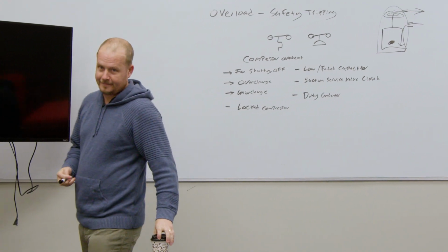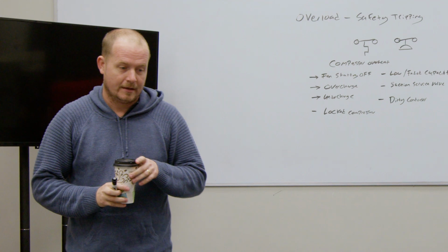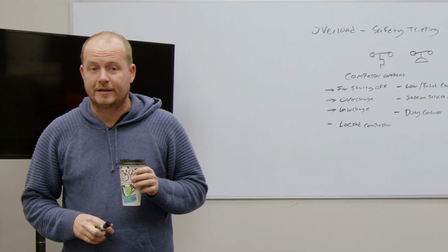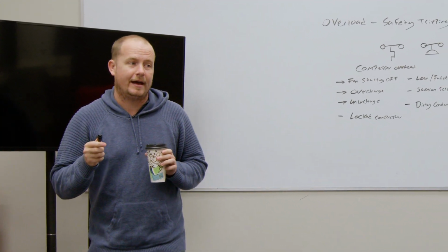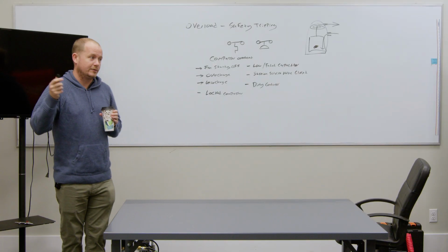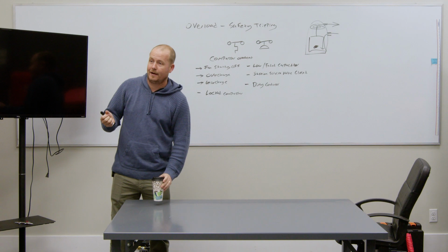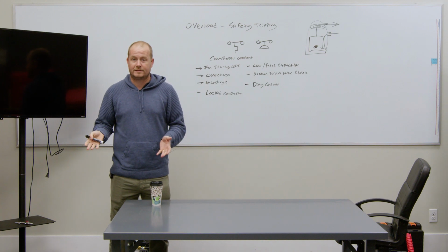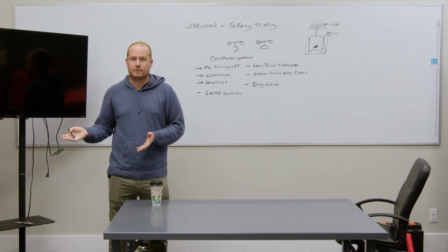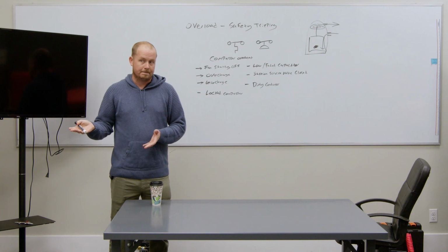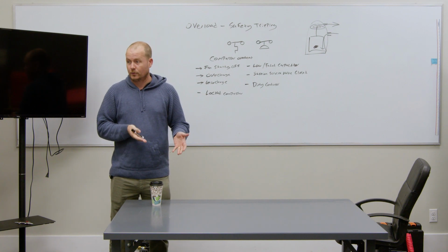Isn't the amperage lower on undercharge sometimes though? Amperage, yes, and those two things aren't the same. So the idea that overheating always comes with overamperage is not correct. In this particular case, you can have low mass flow rate, meaning you don't have a lot of refrigerant moving into that compressor, and your compressor will draw lower amperage, lower current.